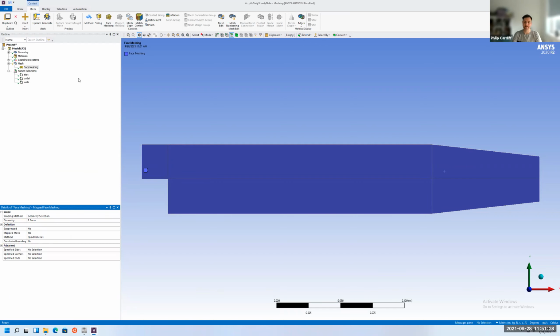That's fine. The last thing we're going to do in the mesher is, because it's turbulent flow, the boundary layers are going to be quite thin. At a physical wall, the velocity is 0, but then within the flow, it's obviously non-zero. So you'll typically get a profile, like a logarithmic profile of the velocity going parallel to the wall. In turbulent flow, this layer would be quite thin. So I'm going to refine my mesh to make the cells smaller near the walls than in the main flow, to better capture this.